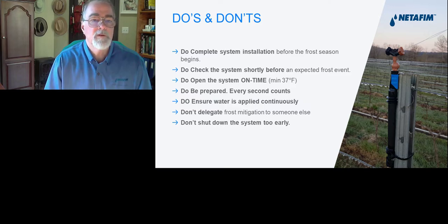We have to keep our water supply continuous. We don't want to delegate this to someone else. We want to make sure we're on site. We're going to be there. We're going to call it. We're going to tell it when to start, and we're going to be able to communicate with small radios, cell phones, whatever it takes. And don't shut the system down too early. We want to make sure that the temperatures are starting to rise, and as that ice starts to melt, that we don't create that very first thing that we talked about.